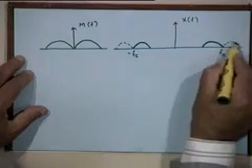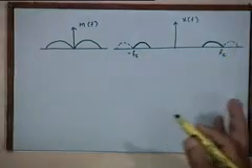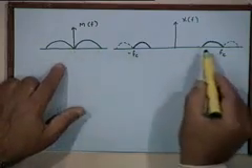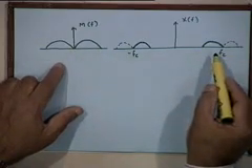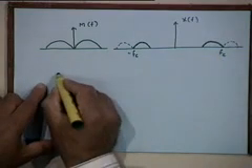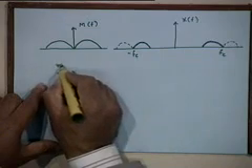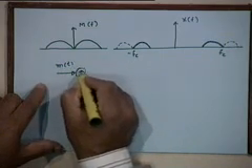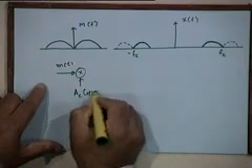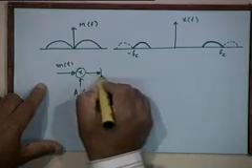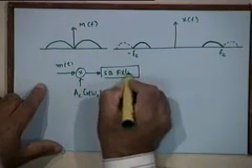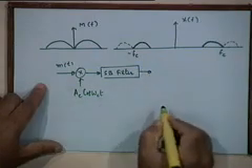So this portion of the spectrum is being filtered out at the transmitter. You first generate the DSB-SC signal, going through the normal modulation process, and then through a suitable sideband filter, like we discussed yesterday, eliminate one of the two sidebands.